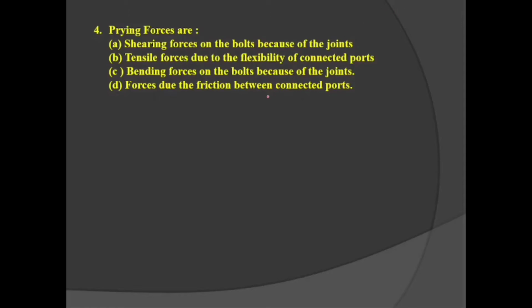Likewise, if these two portions have to be connected, and due to the tensile force some flexibility occurs here, the forces responsible are called prying forces. So you can say, the tensile forces due to flexibility of the connected parts. These are the connected parts.